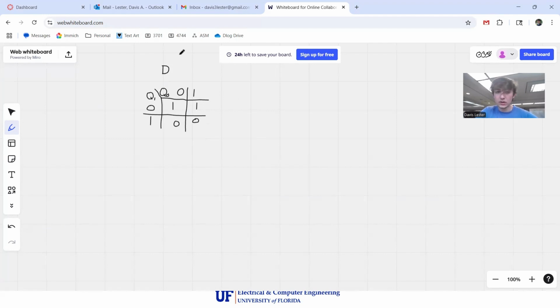Okay? So this is the K-map, and with K-maps, you try to make the biggest circle of ones. I can see these two, which is a pretty easy circle. Because Q0 is changing, Q0 can be both 1 and 0, we can ignore it for the output, which means that the output would just be Q1 naught. Q1 naught equals D. So in Quartus, now I can just take Q1, invert it, and put that into the D flip-flop, and it's going to generate our next state.